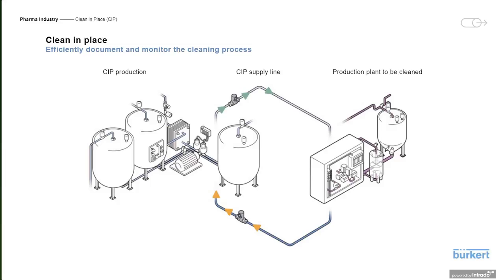So whether it be the caustic soda wash or the acid clean, it's going to be able to detect even the slightest change in concentration. And an added benefit, it's going to be able to give you some idea of entrapped air or bubbles, because I know one thing you have to worry about in CIP systems with detergents is foaming.